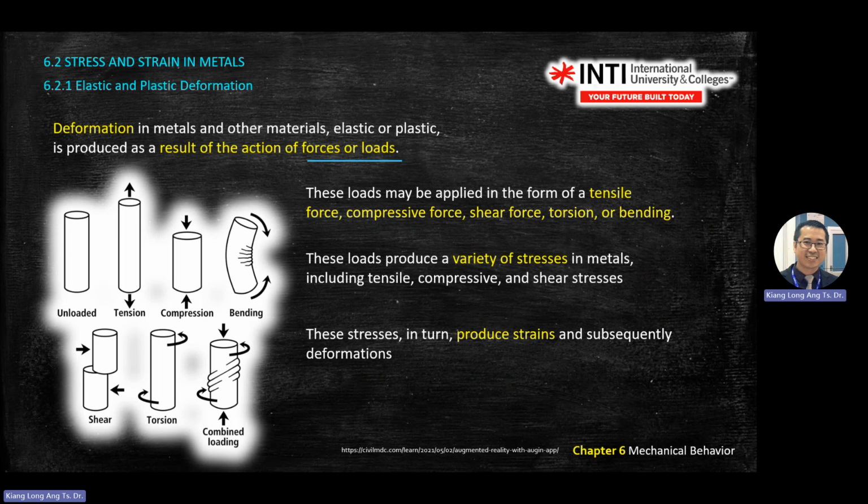You calculate the deformation. For example, what deformation can the object undergo? It elongates, meaning you measure the change of length. If you pull metal, it will have a reduced diameter in the center. If you pull, it will reduce the area. That is also strain. There's a formula for that.